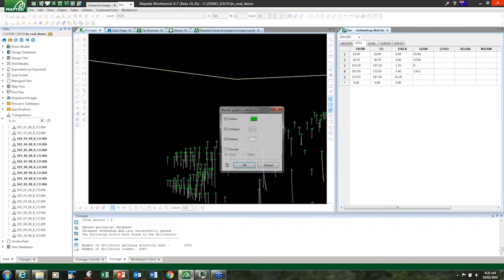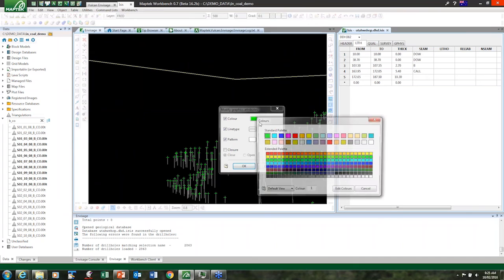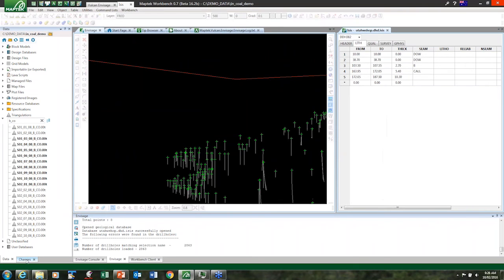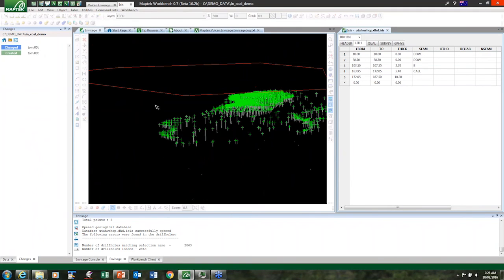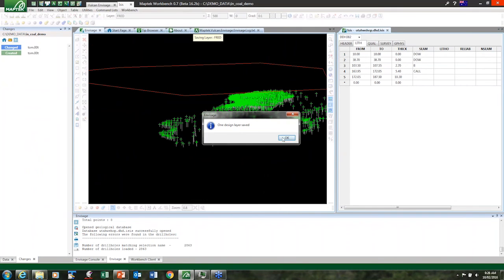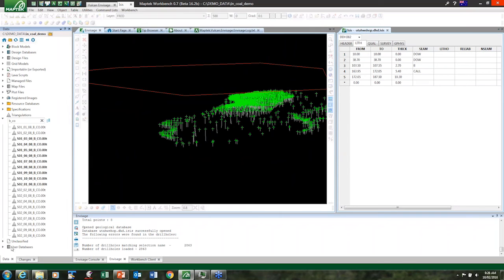If I change its properties to say a different color, I'm building up in the change set, as I mentioned before, because I'm actually interacting backwards and forwards with the data. As I change things, we're picking up a bit of audit trail. So I've loaded a triangulation, I've changed it, I've created it, I've changed it. If I change the layer, that'll appear on there when I save it. And you basically start building up this entire audit trail of what you've been doing in your session.